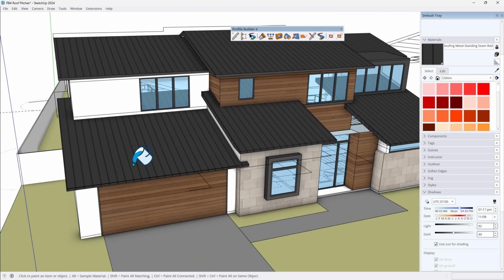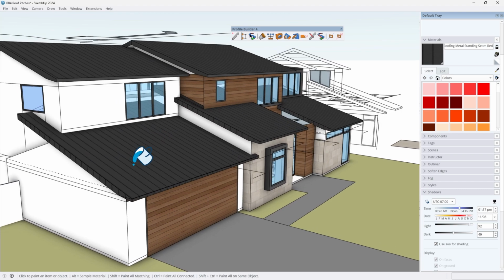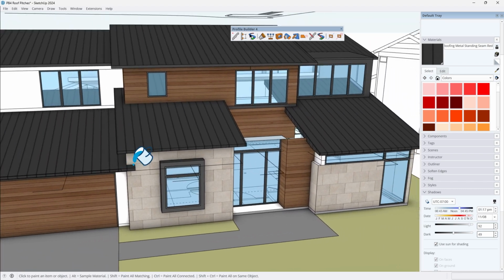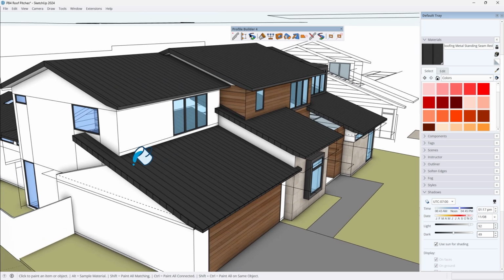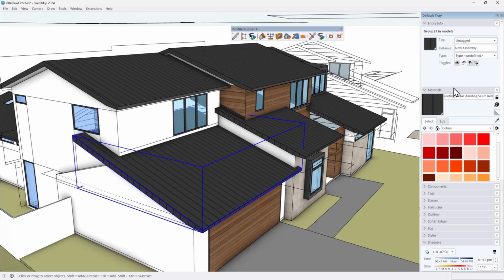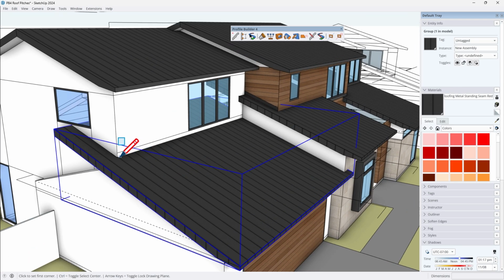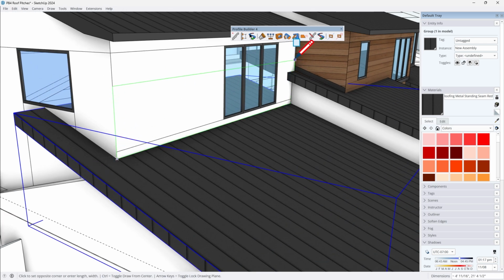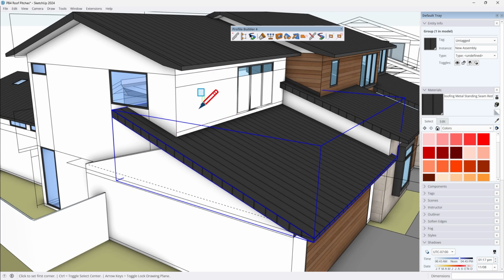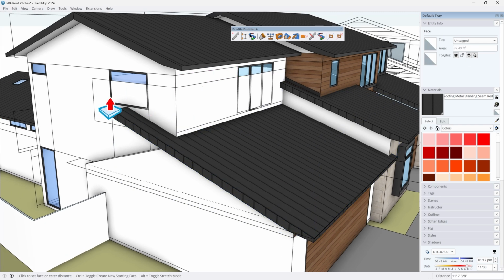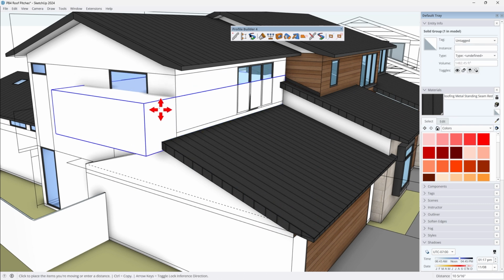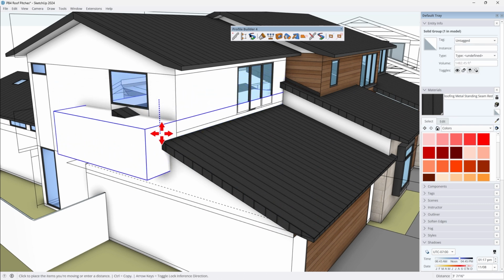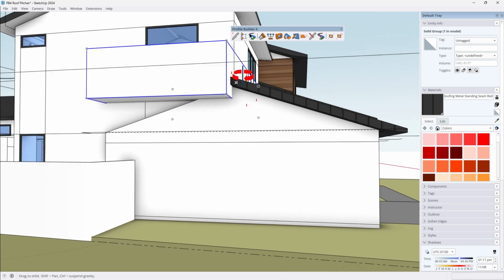And now here, based off of what I'm building, I can now break the live part of it depending on what I need. And one way that I like to do this, particularly with profiles, is I like to use solid tools. So I may draw an existing rectangle. For example, from here, I may just draw a rectangle like that, push it over and push it out. And then I'll triple click and group this and then move it down. I'm moving it down so that it's essentially creating sort of a cut plane for that.